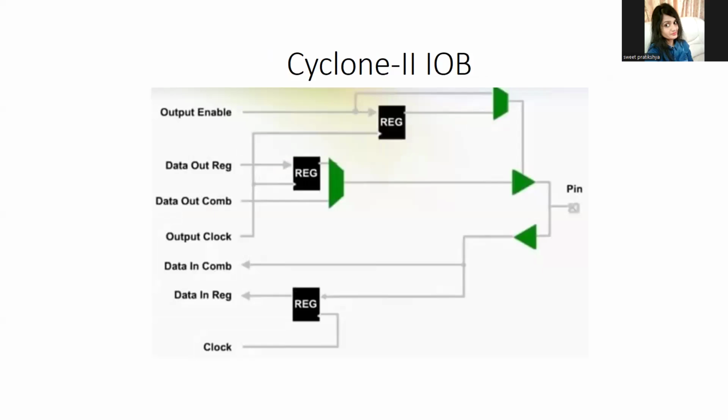Coming to the Cyclone input output block architecture. One by one, we are discussing the internal and detailed structure of each block. So what are the input output blocks? These are the blocks where the internal signals are connected to the outside peripheral devices, like processors or systems. It handles combinational input, that means it directly receives external signals into the FPGA, suitable for simple input.